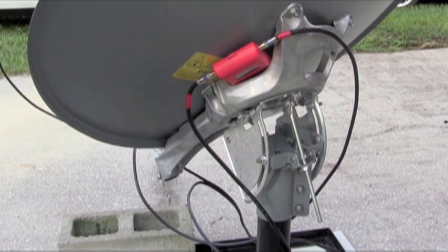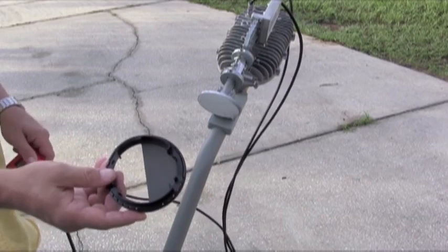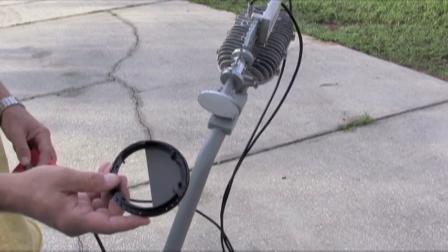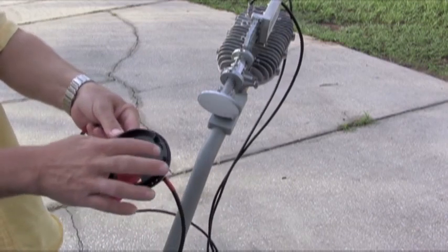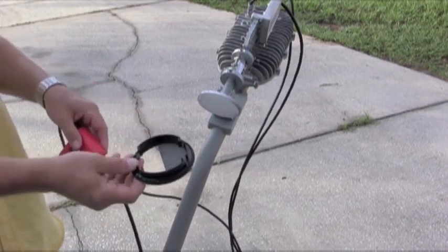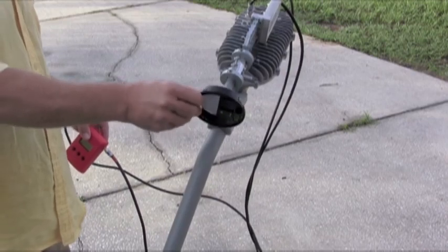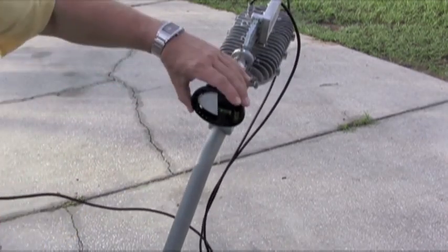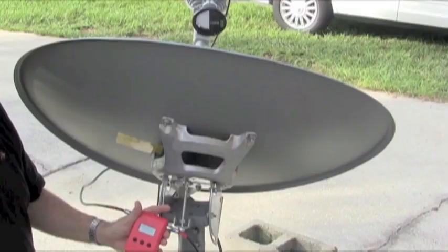pointing process. This involves using a squinter to find the center of the beam, and the squinter is specific to each feed horn. Shown here is the A squinter, which is for a Prodelin oval feed horn, and here are the clips that attach to the actual feed horn. So we're going to go ahead and clip that on. We're going to start with the opening on the left side. It's very, very important to be consistent and always start and use the squinter the same way each time.